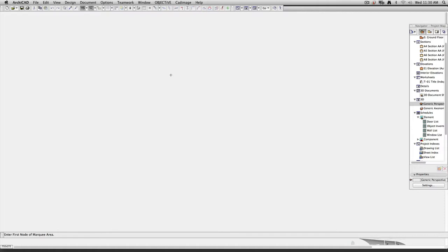Because all of those houses and buildings are just outside of the study area and they're just big blocks, just have them on one layer. You can switch them on and off. It's totally up to you, really, at the end of the day. But do have them on different layers. Yeah, I've got quite a lot of layers running at the moment. That's really good because when it comes to doing your plans and you want to see the building footprints, not a problem. You can turn on their buildings and you'll see all the building footprints.